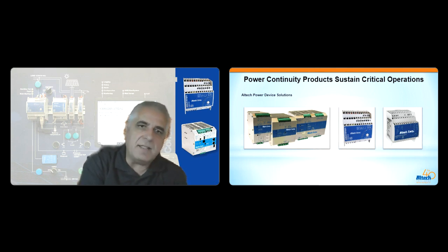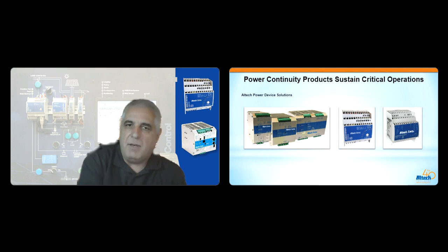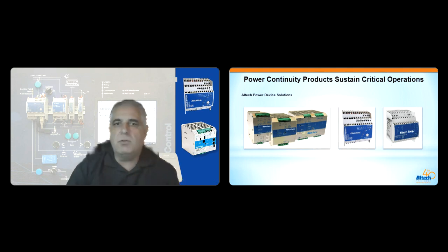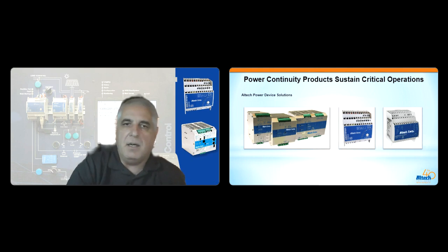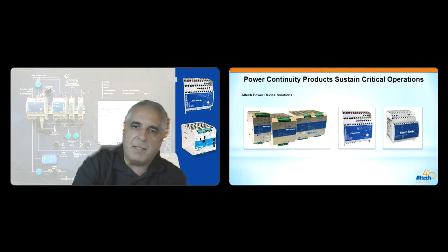What else? We also have to mention the battery type and runtime. When you are choosing a DC UPS, consider the type of battery used in the UPS and its capacity to provide backup power. Choose a UPS with sufficient battery capacity to support the required runtime of the load.